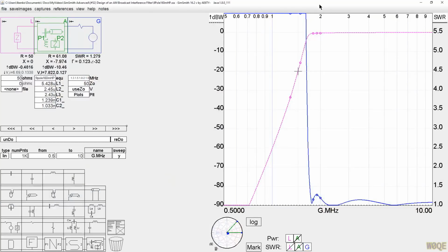It is designed to be a transmit 100 watt plus level of 100% duty cycle over the full HF range. It's intended to have an attenuation below 1.3 megahertz of 30 dB, and it meets below 30 dB, and from 1.3 to 1.5 megahertz of 15 dB.